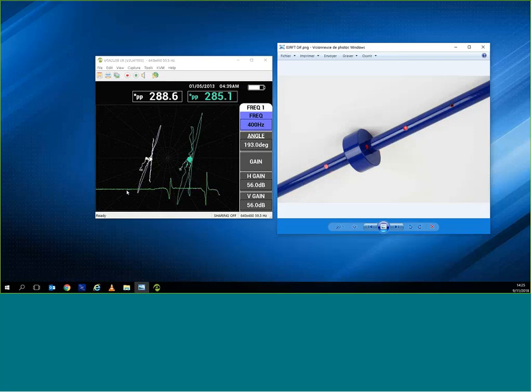We see the other defects. Now here I'm going to get close to the support. So that's the support signal. All right. So I'm going to erase that. And what I'm going to do now is I'm going to put the support close behind. So it's about halfway covered. So the hole is halfway covered by the support. I'm just going to redo the same test. I'm going to erase. And we're going to scan slowly but surely.